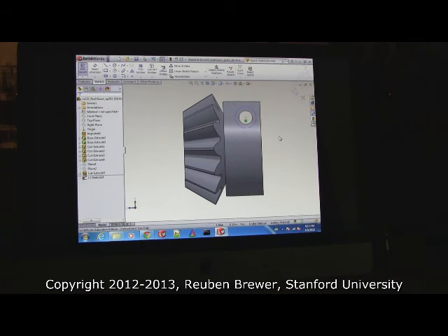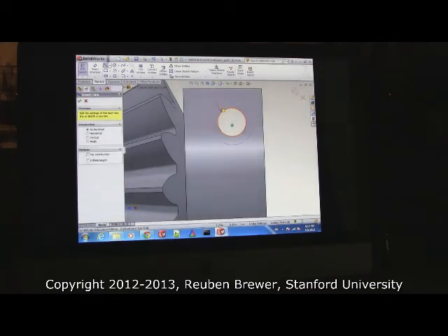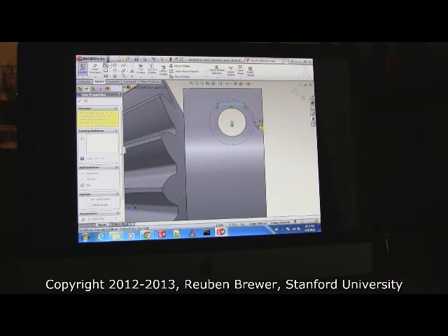How big should it be? Doesn't matter. We're going to size it in a fancy way in just a sec. Okay, now take a solid line. We're going to make a hexagonal hole. So click here and let it auto horizontal and then click on the circle. Then, watch this. I come down here until I smack on that point. Then I go down anywhere, that's fine. Auto align horizontal. Go up to this point that it constrains there.